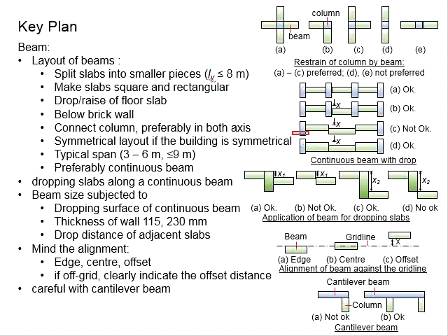The best way for you to design it, you will need to make sure the soffit of the beam for the entire continuous member, if there is no column in between, needs to be at the same level. But if you have columns in between, then you are allowed to do so, because every single member here will now be considered as a simply supported beam.